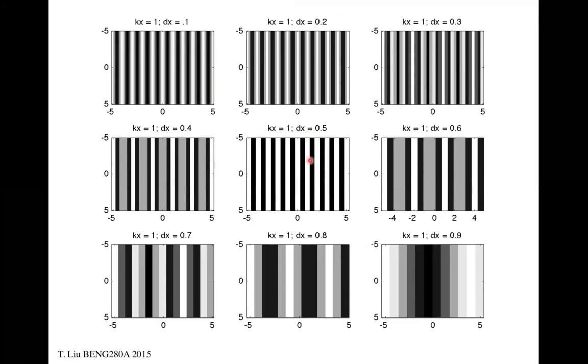So now I have a peak and a trough, and a peak and a trough, and a peak and a trough. And that's perfectly sampling up and down, up and down, up and down. And this, in fact, is where we hit the Nyquist criterion. So it's 1 cycle per millimeter. My sampling rate has to be 2 cycles per millimeter in order to represent that sine wave adequately.